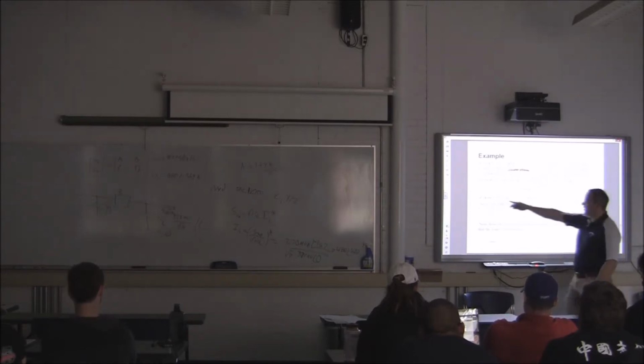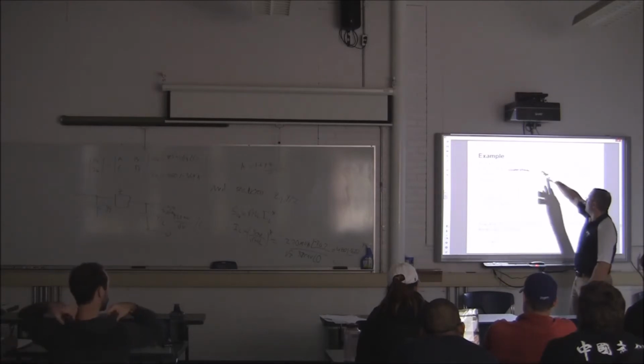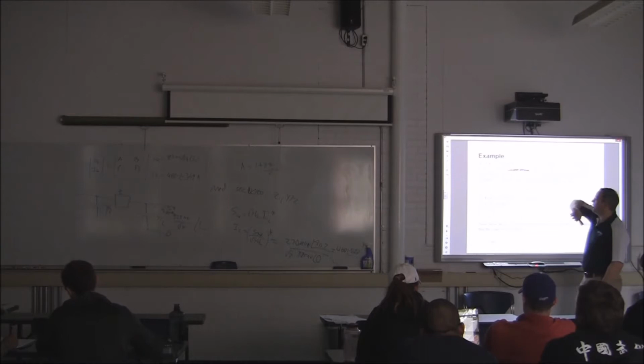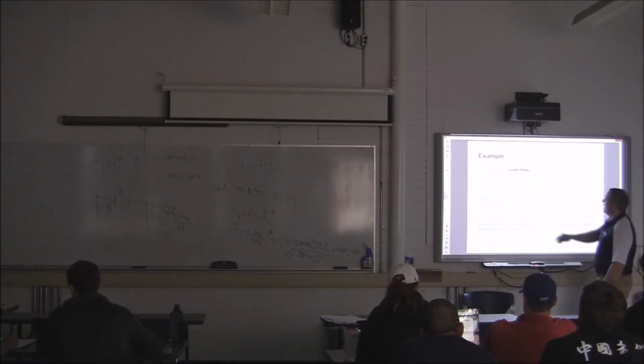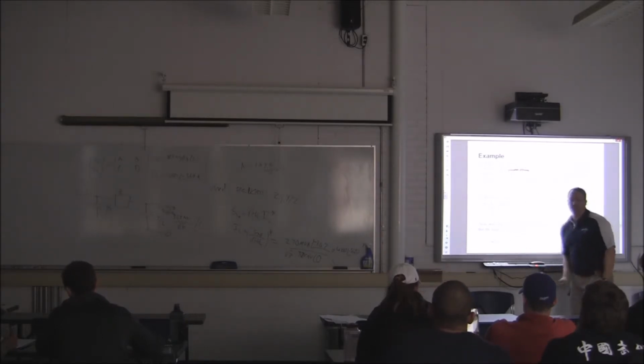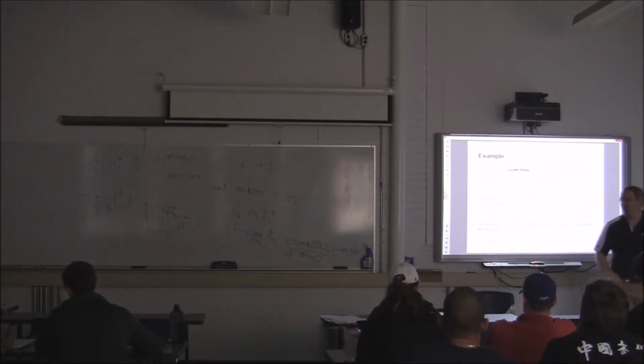I solve for Z, so it's just going to be my resistance, which is 0.36 times 130, 4.68. And my J term is going to be stolen from here, and since it's an inductor, I put a positive J. That's my Z.